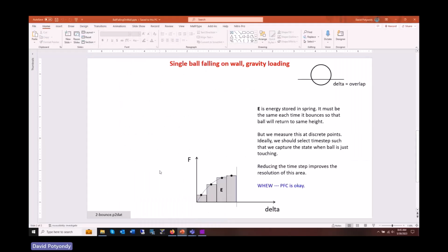So this is a collision problem. And for this particular problem, we want this collision to properly conserve energy and be correct. So what that essentially means is, if you want that to happen, you're going to need to force the time step to be really, really small so that you resolve the collision, right?